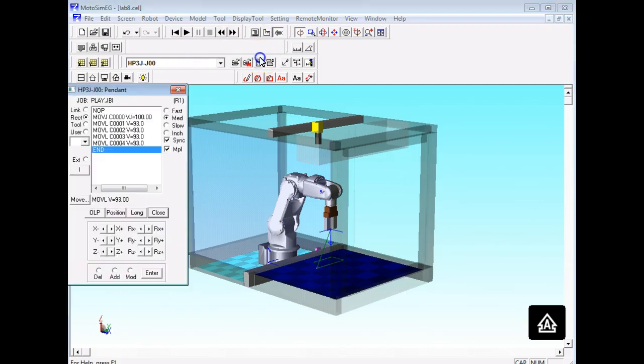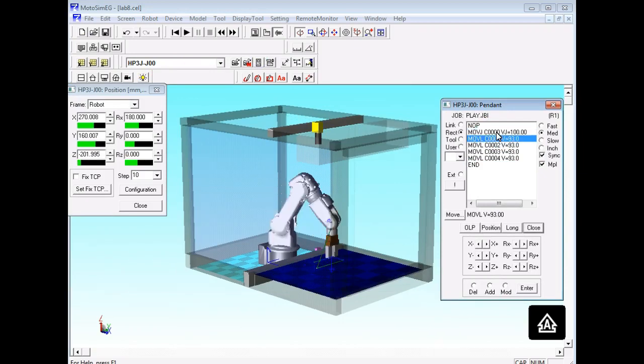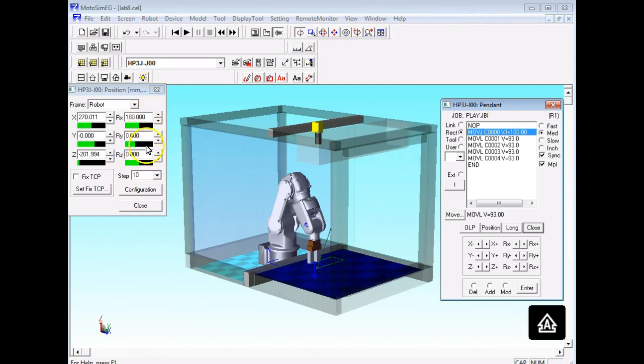So if I single step through the program, on this one it's not very hard. You can see the actual Cartesian system changing up there. So when I save that point, this is the way it was stored. It's stored in XYZ, which we have a basic understanding of now, and then the orientation of the tool. Roll, pitch, yaw. We looked at that yet. So these over here are in angles. So roll, pitch, yaw is given in angles, and then the XYZ is usually given in millimeters.